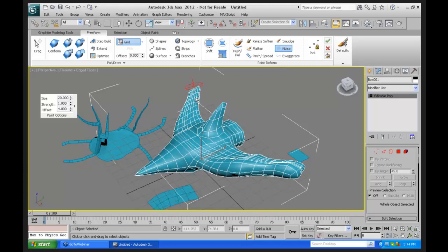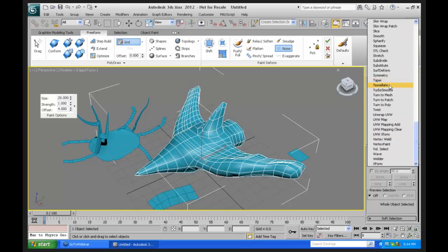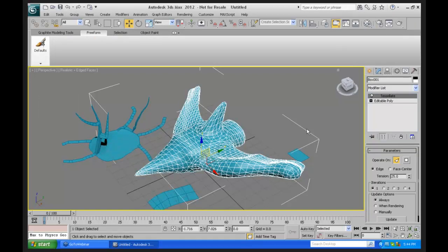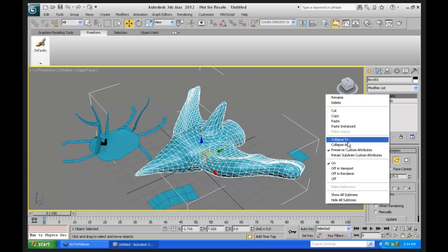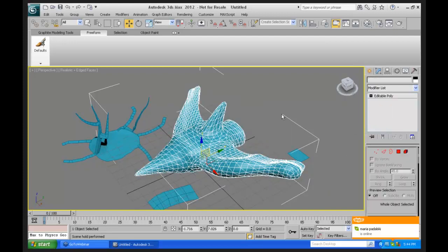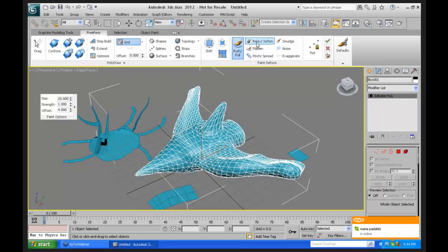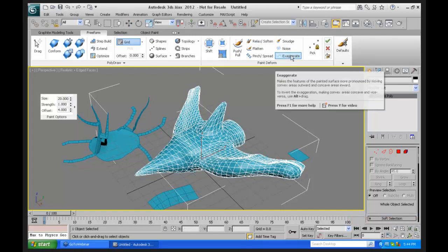This geometry is not complex enough for me to edit like this, so I'm going to do something to it. I'm going to tessellate it. There we go. Now I'm going to collapse it again. Unfortunately, the collapse goes to mesh, and then I make it an edit poly, and now I should have the ability to use exaggerate, and it should work better. Okay, why doesn't exaggerate...